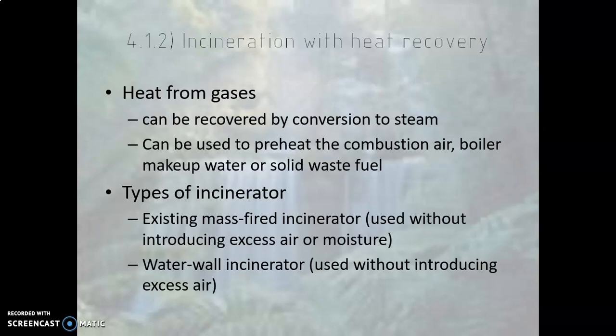Incineration with heat recovery can be done by conversion to steam. The heat that is released from the incineration can be recovered by using steam, and can also be used to preheat the combustion air, boiler make-up water, or solid waste fuel. So the heat will not be wasted, it will be reused, by conversion to steam.